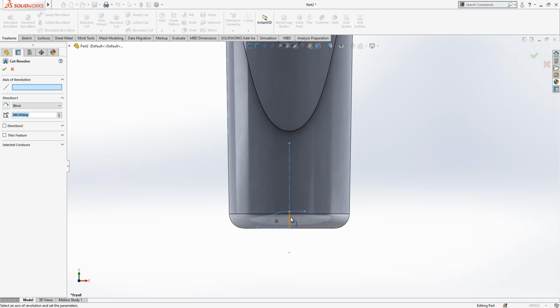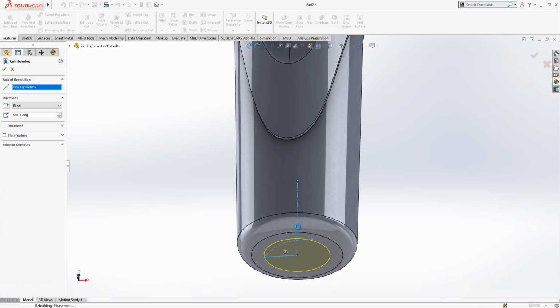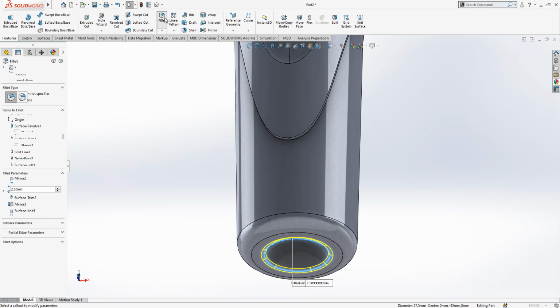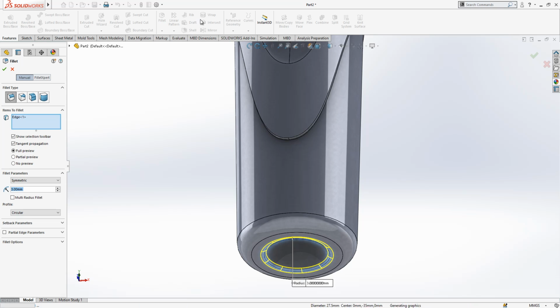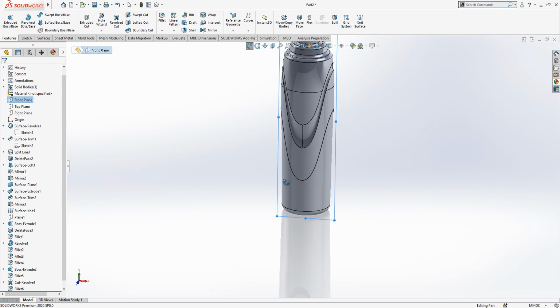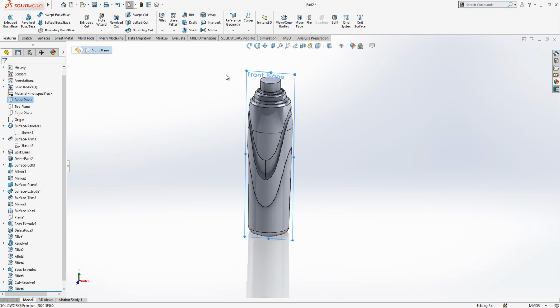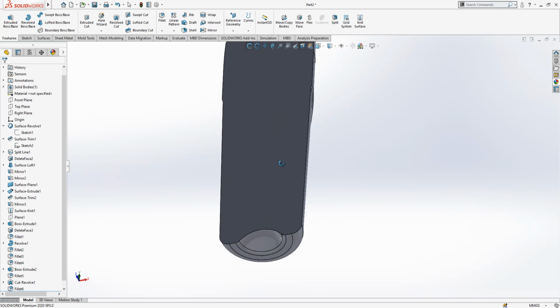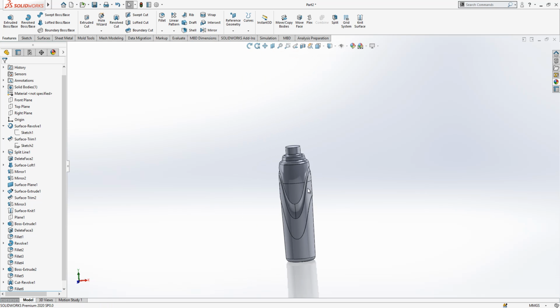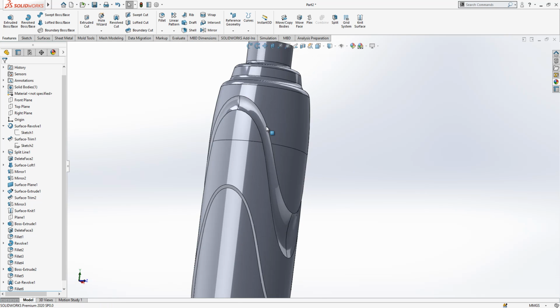Revolve cut. This is the axis of revolution. We will have this nice cut there and 3 radius. Whatever radius you define, if you want to have radius everywhere after the shell operation, that radius should be bigger than your material thickness. Don't forget. This is a little bit exaggerated, but yeah, tutorial. Let's go ahead. Not so much importance right now.